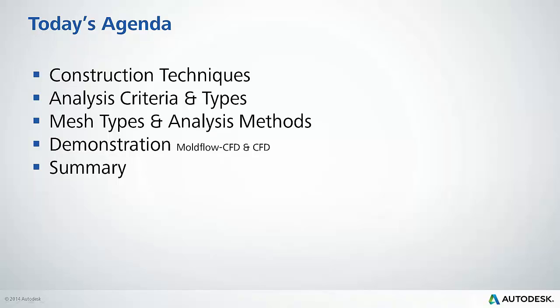So, cooling is important to us because it does consume 70 to 90% of the cycle, and it depends on industry, more importantly, your aspects or your criteria that you're focusing on as far as the product requirements. It does affect quality, like surface finish, residual stress, crystallinity, and it affects our bottom line, right? Production costs, how soon does that part reach temperature for ejection, cycle time.